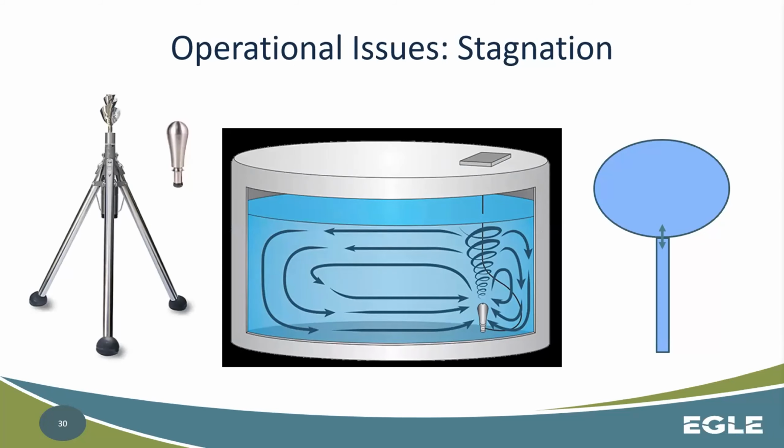Some of it goes into the direct design of a storage tank, and then some of it goes into add-on portions, right? Whether that's diffusers or mixers, these are a couple of examples of that. You're trying to stir that up, trying to move that water around, so you're not just short circuiting it, where water goes from the inlet directly to the outlet.